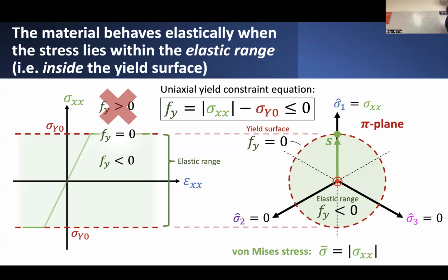So you can imagine if, let's say, this yield surface is expanding due to isotropic hardening behavior, then these two limit lines are going to get further away from each other. However, if I have shifting of the yield surface, kinematic hardening, then it's going to look like the whole domain of behavior in which elastic behavior will occur will shift up or down depending on the direction of loading that I'm putting on this whole thing.